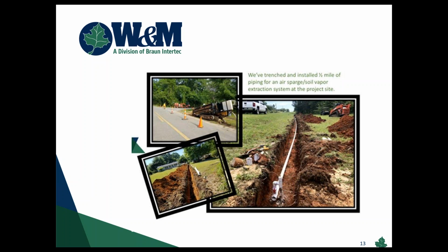So basically the long pipe's going to be pushing air into a well that's screened below the contamination in the groundwater, and that air is going to evolve out of that well and spread up through the contaminated groundwater, a lot like setting a tray of gasoline out on a hot sunny day and watching it evaporate. That air coming through there is going to volatilize or strip out the contamination from the soil.